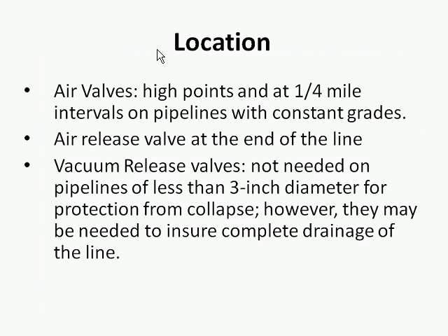Vacuum release valves are typically not needed. They're there to keep pipe from collapsing from a suction or a flow back. Pipes less than 3 inches diameter typically don't have that problem. But I mention it because it's important to think about and make sure that you know that it's not needed.